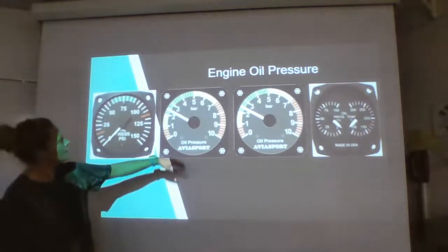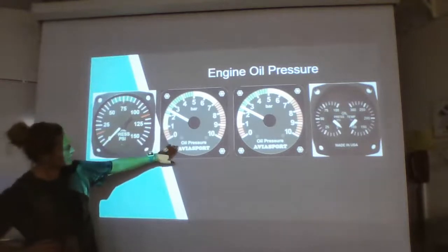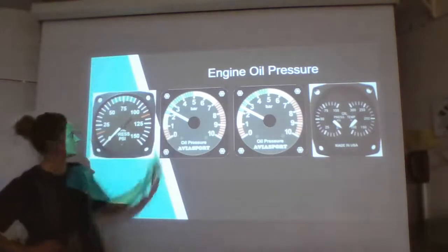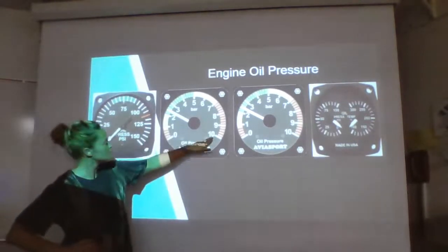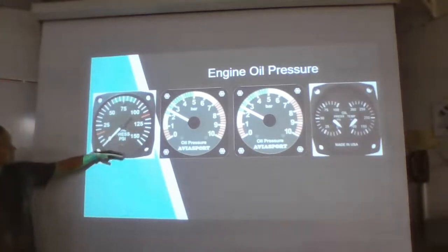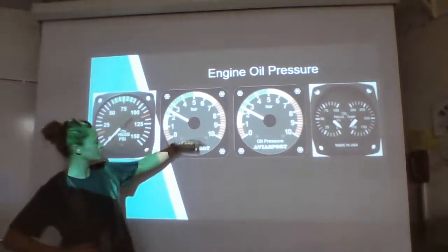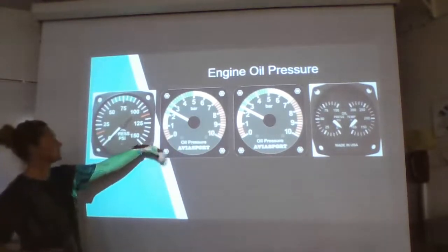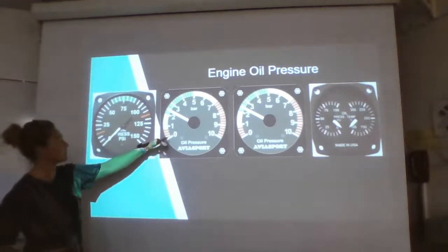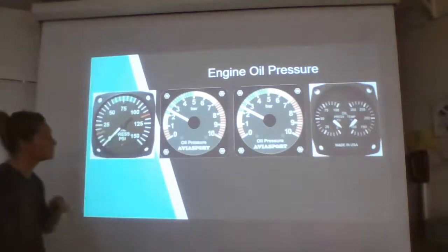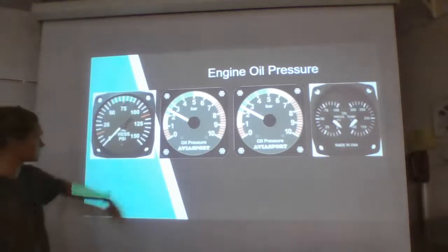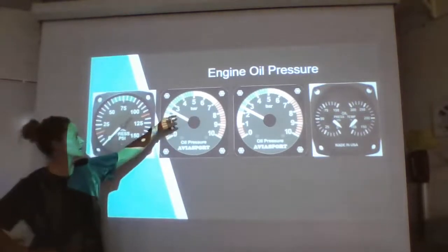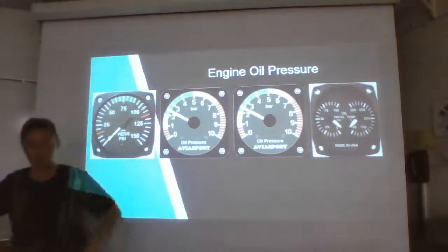So you also have 2 of these oil pressure gauges here that you may see. The whole thing has some kind of color code system. So it goes from 0 to 10. So it's using a different format of the numbering system of how to read it, okay? So we still have our red areas. They're marked out in a little bit of a bigger area. So we have our minimum and our maximum limits that we don't want to go below or above. We also, in this one, have the caution area. We have our yellow on both sides, and we have our normal operating range that we optimally want to stay in.